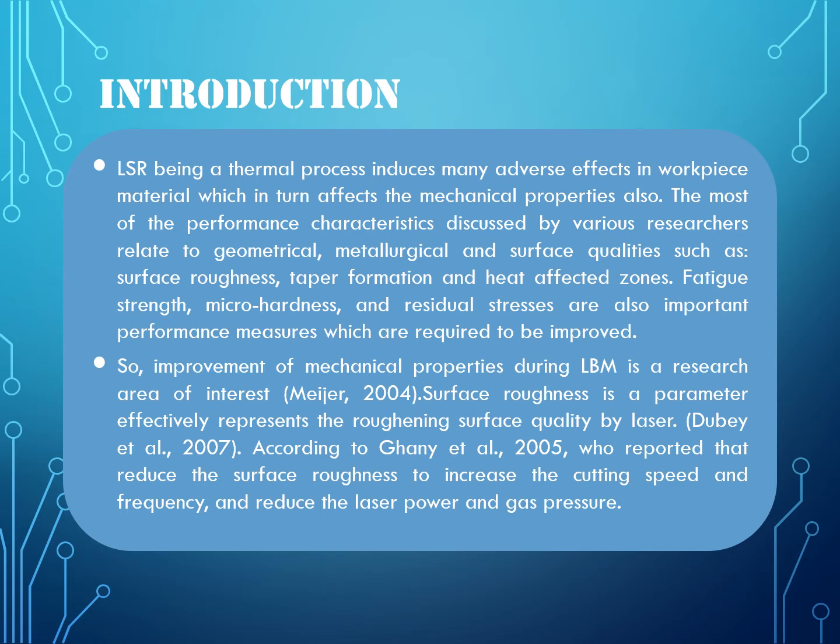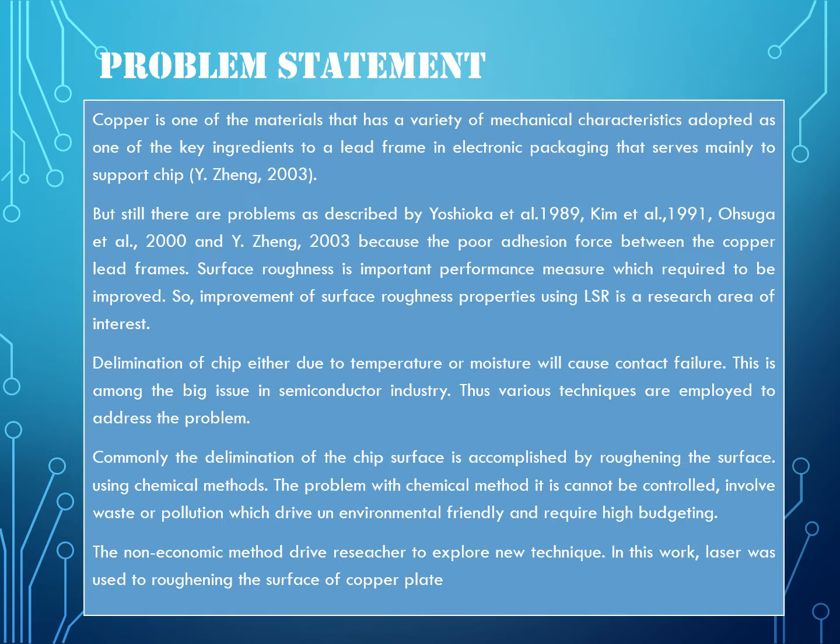Improvement of mechanical properties during laser beam machining or laser surface roughening is a research area of interest. Dubey in 2007 reported that surface roughness is reduced by increasing the cutting speed and frequency, and reducing the laser power and gas pressure.